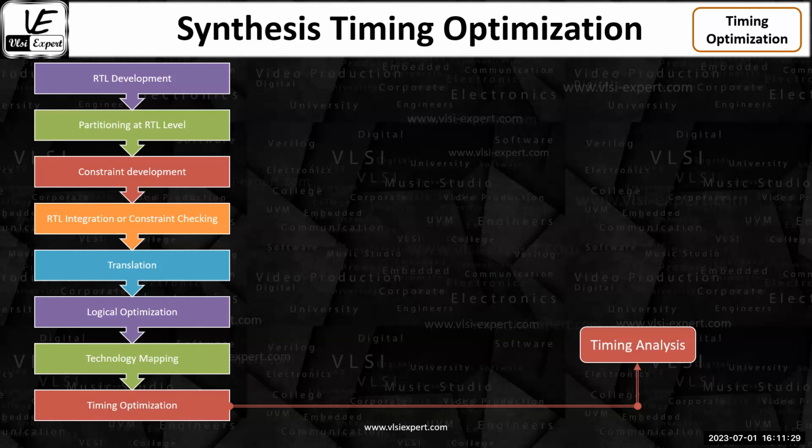Then the tool does the timing analysis, checking whether it is meeting the constraint or not. It checks how much time it will take to give you the output. You gave the constraint that it should give the output in 6 nanoseconds. The tool figures out that using NAND 1, it is giving the output in 10 nanoseconds. That means there is an issue, there is a gap. It's supposed to work in 6 nanoseconds, but right now it is giving the result in 10 nanoseconds. So after the timing analysis, it figures out whether it is pass or fail.